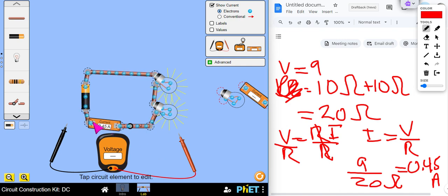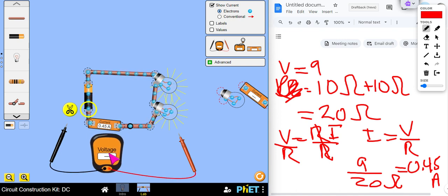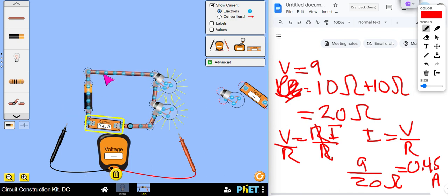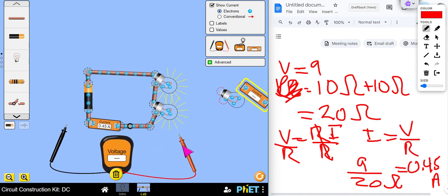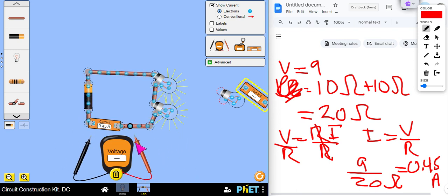This is the current. The ammeter. The ammeter is measuring the current in series, meaning the electricity is flowing through it, like this. Now we have a voltmeter sitting here. When we're trying to measure voltage, we have to measure voltage in parallel, meaning we're not letting the electricity flow into here and connect it so it can flow out.